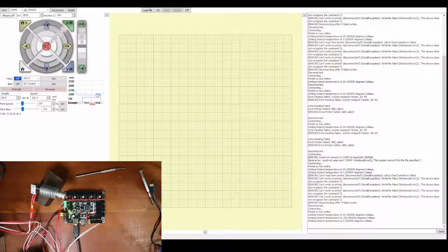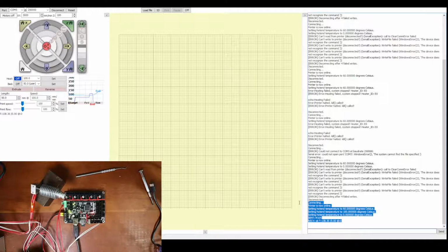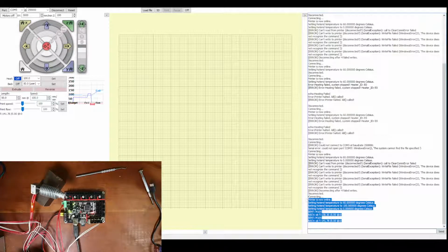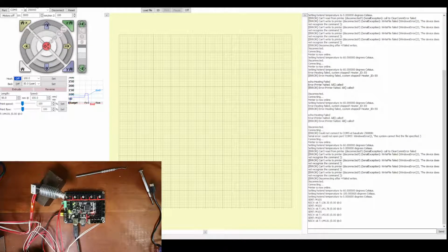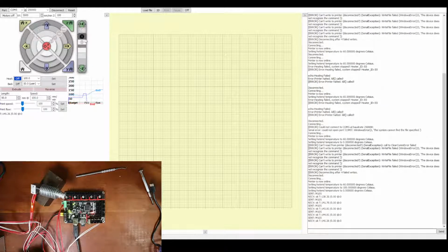But essentially that was a pin conflict where another pin was using it. And you may be able to see the same issue in here on occasion with the debug setting, where you'll actually get more of a readout. This is why I use Pronterface as a tool to troubleshoot, because it's got some functionality in it for debugging. So essentially I can turn that back off so we don't get all the messages, but that's why it's so helpful to use that. Let me check on the chat because I've been talking way too long.